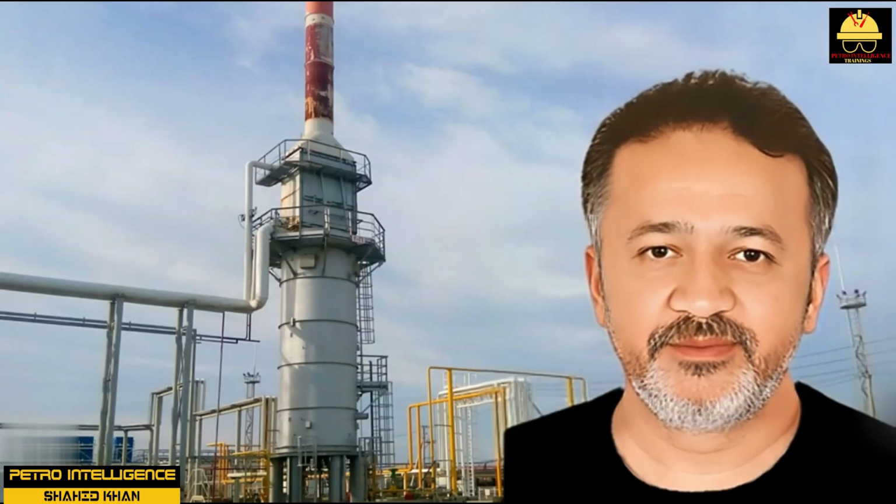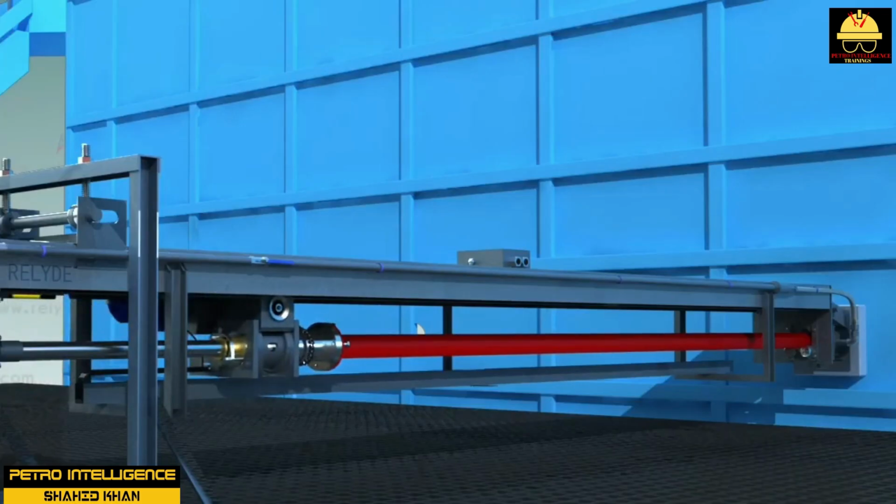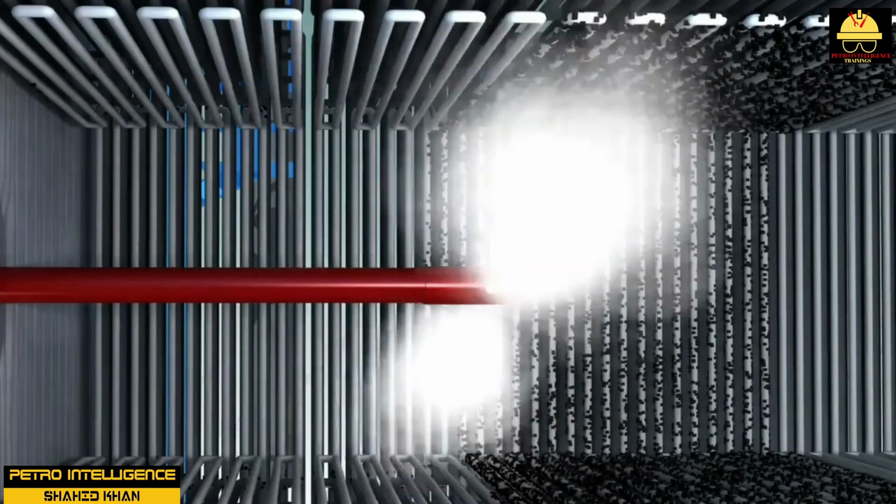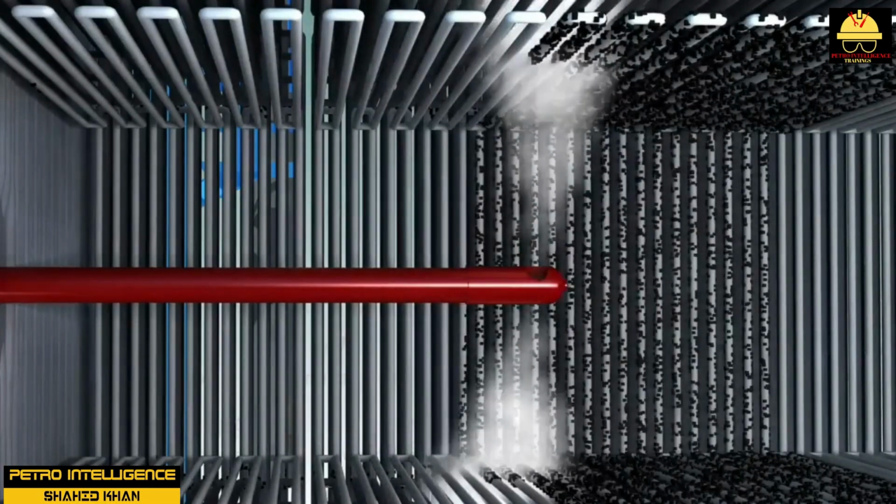Soot blower. Soot blowers are devices found in the convection section of process heaters. Soot blowing is required when the efficiency of the convection section decreases. This can be calculated by looking at the temperature change from the crossover piping and at the convection section discharge. Soot blowers utilize a transfer media such as nitrogen, water, air, or steam to remove deposits from the tubes.